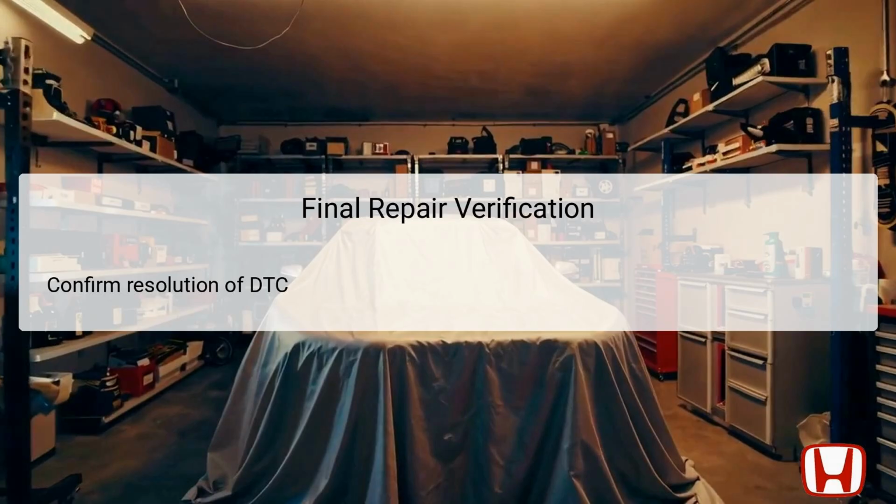Using the Honda Diagnostic system, HDS, again will confirm whether the repair was successful by checking for the absence of the DTC B1C55. If the code does not reappear, you have successfully resolved the issue, and the driver's seat heater should be functioning correctly. However, if DTC B1C55 does return, further investigation is necessary to identify lingering issues with either the seat heater control unit or electrical connections, ensuring that reliable heating performance is restored.